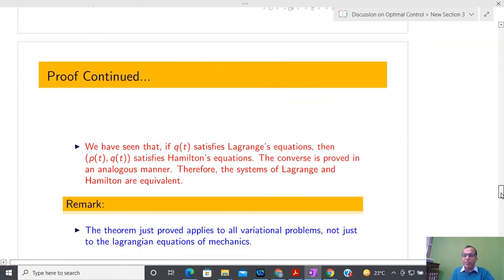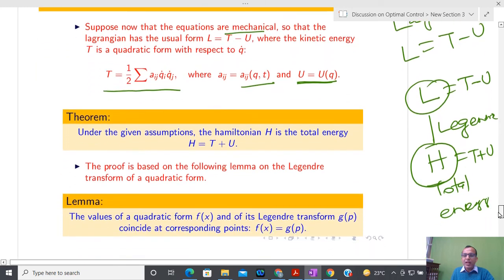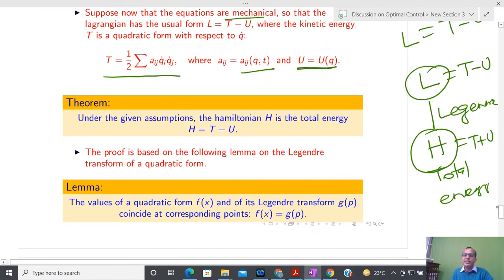So particularly for a mechanical system, I have a clear-cut physical interpretation: kinetic energy and potential energy. I will calculate the kinetic energy and potential energy, add them, and substitute in the Hamiltonian formulation, and that will give us the state space representation, or dynamical equation, of the mechanical system.